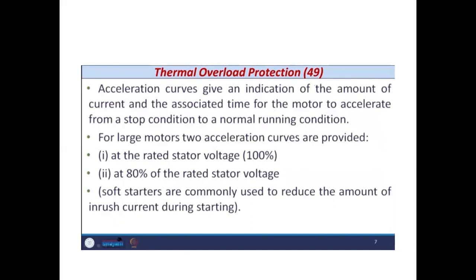Okay, so when you start the motor, it is at standstill condition. After getting to its final base speed, whatever time is required by the motor is known as the acceleration time period. And this time period is always associated with some voltage, whether you start the motor at rated voltage or some reduced voltage. For large motors, two acceleration curves are specified by the manufacturer.